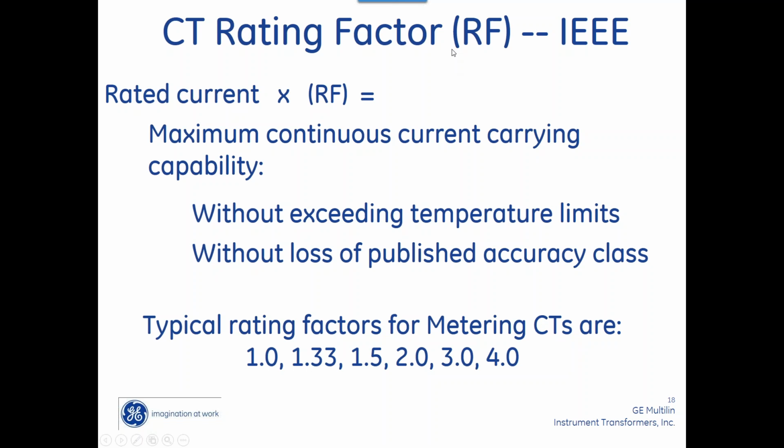Next thing is rating factor. So when I get into a metering CT, I start getting concerned, well, how much can I overload that CT without it burning up? And so that's the maximum continuous current you can carry. So you'll see commonly rating factors of 1, 2, or 4. And I'll actually show you what those look like.